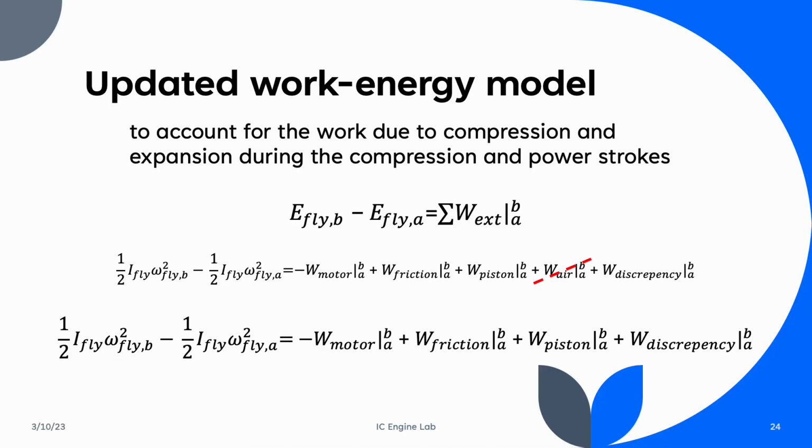Now that the head is on the engine, the work energy model needs to be updated. The work from the piston can no longer be assumed to be negligible due to the engine running through cycles at different pressures. This also introduces a work discrepancy. In an ideal world, there will be no pressure loss between the strokes due to air loss or a bad seal. However, the work discrepancy shows the loss in work due to said difference.